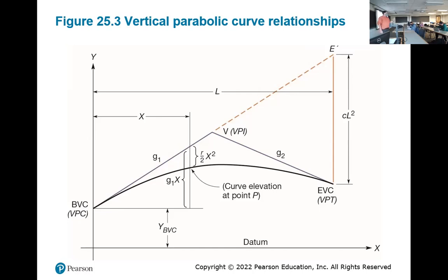But your slope, the one that I just said, 1%, that's 1 foot of vertical elevation change over 100 foot of run. So if you did that in your calculator, it would be 0.01, right? 0.01 as a percentage, you multiply it by 100, you get 1% grade. The equations in the textbook, G1 and G2, are such that it's the percent grade, it's 1. It's not 0.01. Follow? Okay.